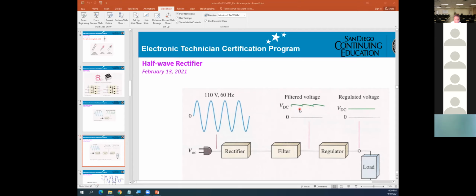Okay, that means the time for the capacitor to discharge and charge. So they still get some, not completely. That's why you get the DC from 0 up to here. On top of the DC, you can get AC ripple. Okay, and then they need to go to the regulator to try to clean it up. So that's why now there will be a clean DC here.